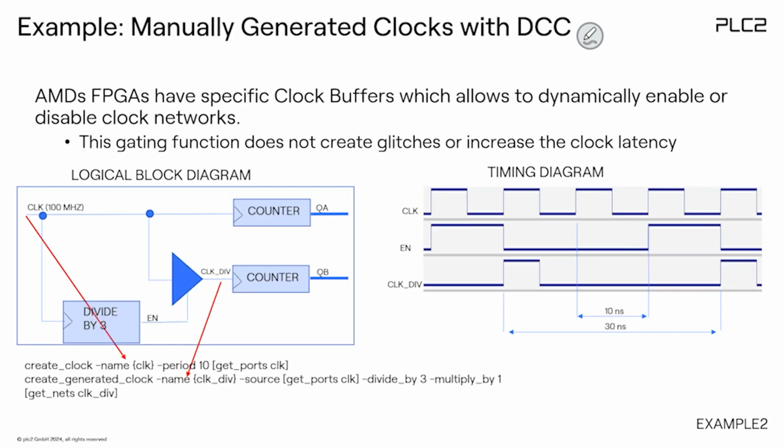Well, for example, maybe first some information: inside the AMD FPGAs we have several different clock buffers. One clock buffer looks, for example, something like this. It's just a clock buffer, there's an in and there's an out. Easy, nothing happens. So this means in and out. But in some cases, you would like to decimate the clock. That means to make the frequency slower. There are a lot of reasons to do this, for example, reduction of the power, optimizing the power consumption.